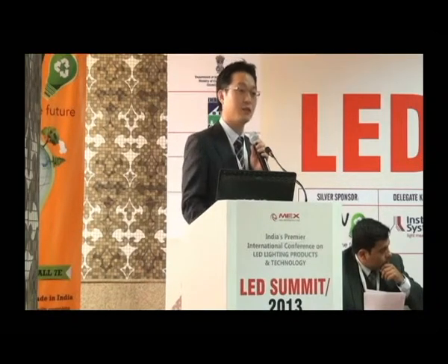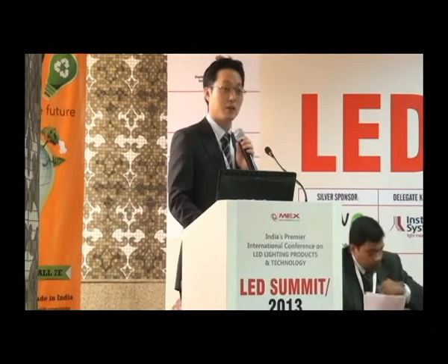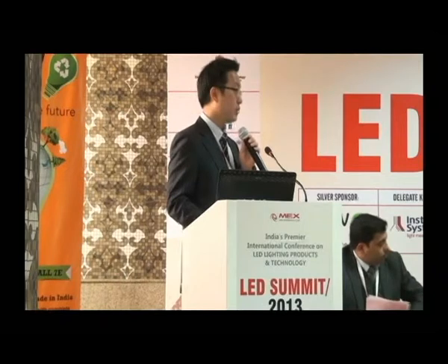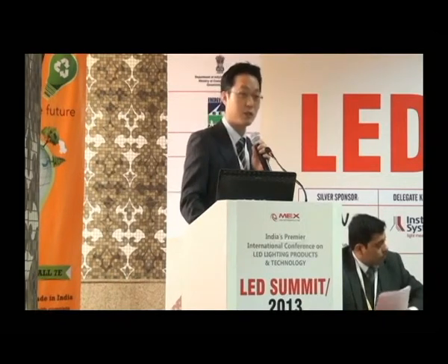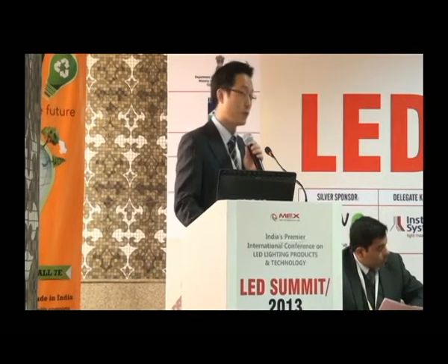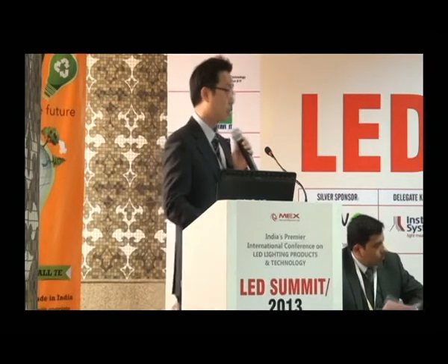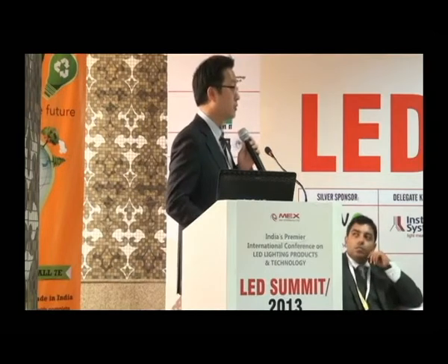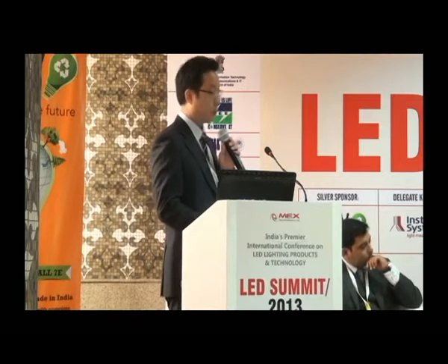The SMT process installs LED chips on the PCB substrate. In that case, all LED chips have to tolerate a temperature of around 260 degrees Celsius for over 10 minutes. Epoxy material cannot survive such a tough processing condition. Only LED silicone material can pass. So at Wacker, we selected these two parts.